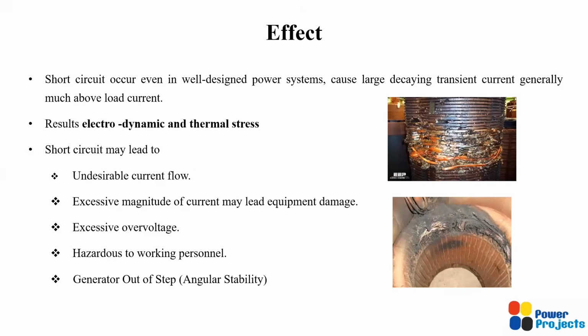And definitely this short circuit is hazardous to working personnel, and this short circuit, specifically in high voltage and extra high voltage systems, may result in generator out of step. That is basically an angular stability issue which has to be covered as a part of transient stability. So these are the effects. In order to mitigate or minimize these effects, we need a short circuit study.